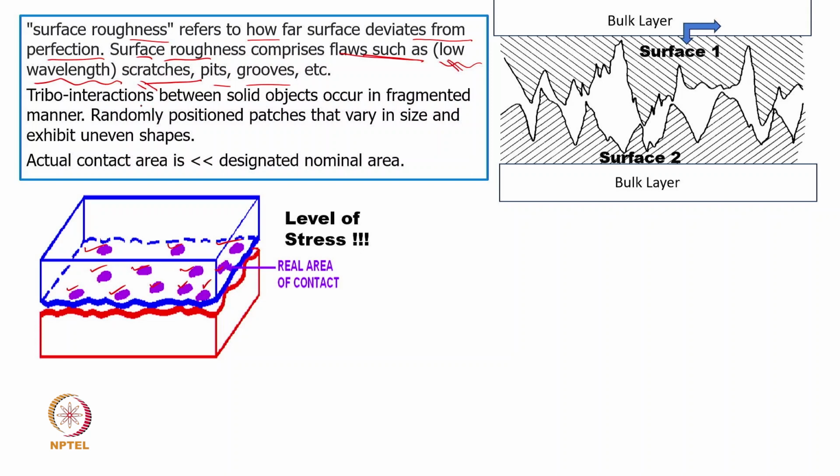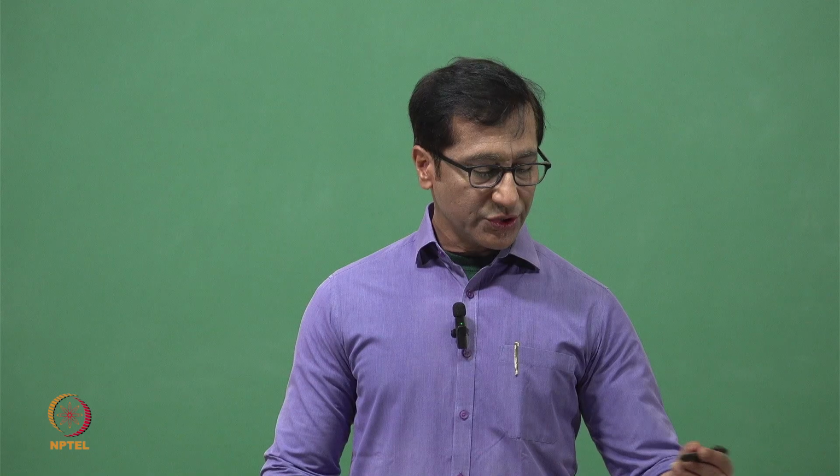Another thing we are saying, the tribo interaction between solids occurs in a fragmented manner. It's not a continuous manner. That means the continuum theory which we generally use for hydrodynamic lubrication may not be applicable for this purpose.